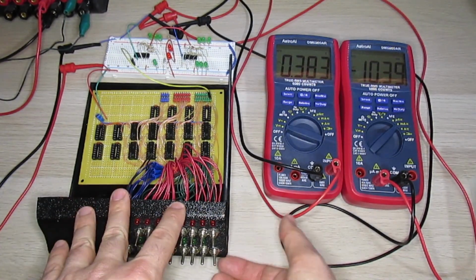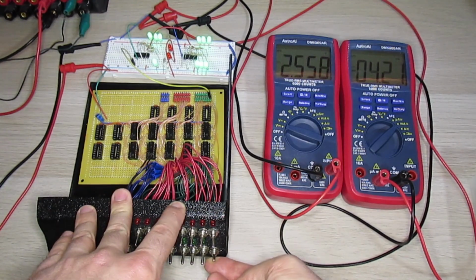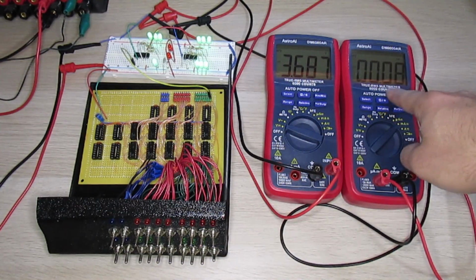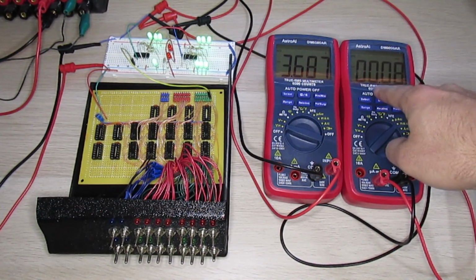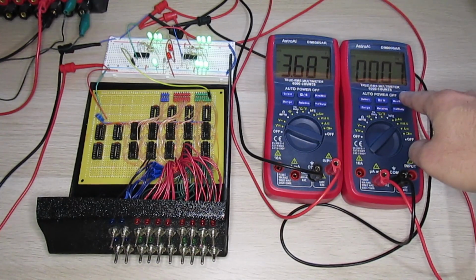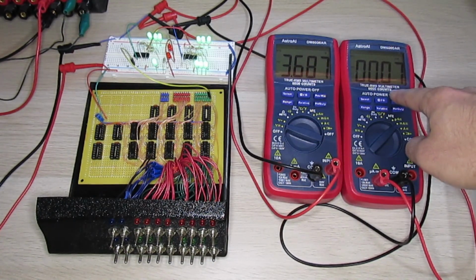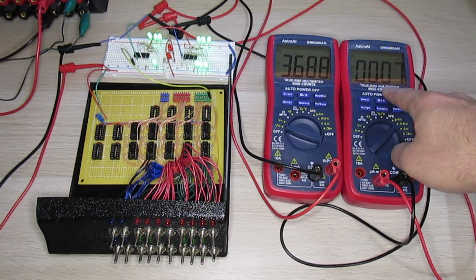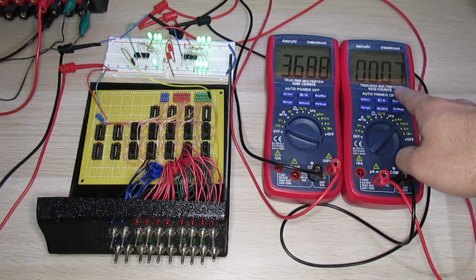And then in the output high state, you can see we're really not drawing very much current at all, 0.08 milliamps, and the datasheet asks us to please not draw more than 0.4 milliamps, so we have quite a bit of wiggle room here.